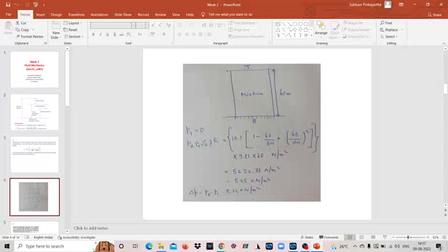For our purpose we assume a constant value of atmospheric pressure, but a simpler way with less calculation is to adopt the atmospheric pressure as the reference level and obtain the gauge pressure. Now at the top, what is the fluid depth? Fluid depth is 0. So the pressure on the top, that is Pt, is equal to 0.